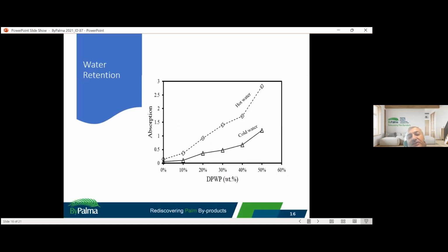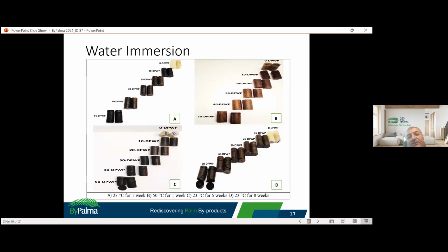insulation applications. Water absorption, you see that here, the water absorption for this composite material is relatively low, which in many cases is less than 2%, even in hot water it is less than 3%. But here we took the advantage of the PLA, where the PLA in general is a hydrophobic material. Therefore, the water absorption is relatively low and it is in the acceptable region.